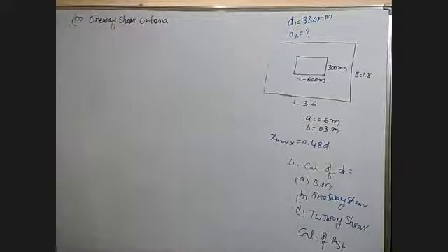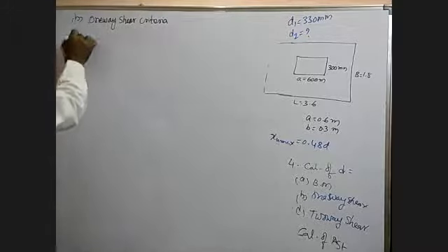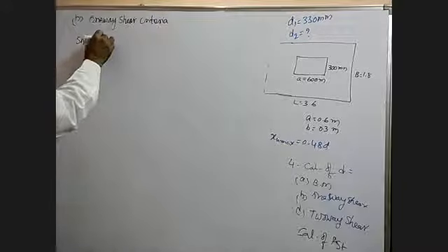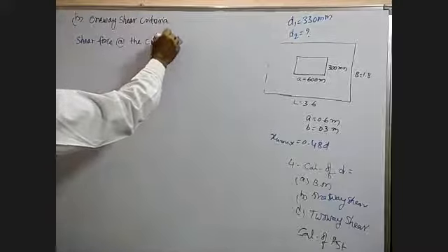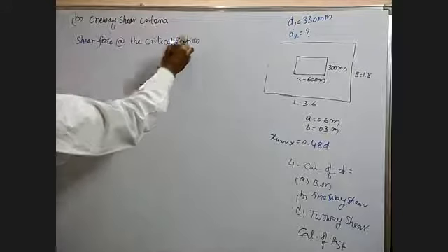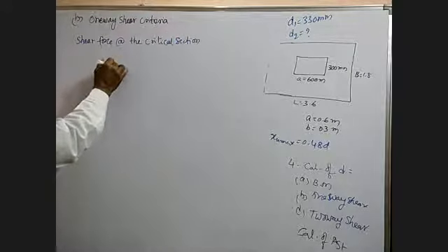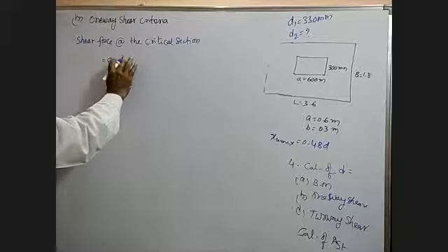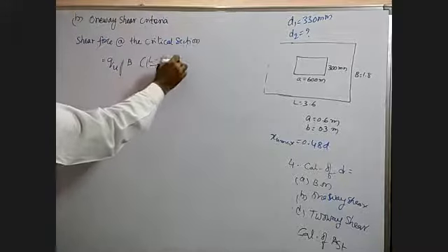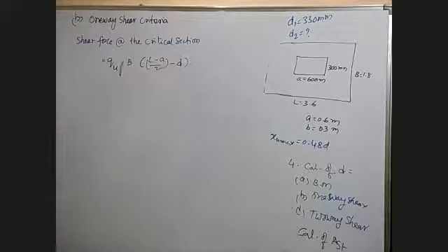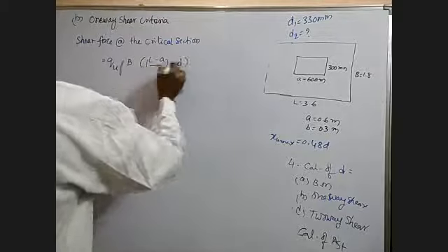Here we have to calculate the shear force, the shear force at the critical section, which is U into B into (L minus A by 2 minus d). Substitute this value.